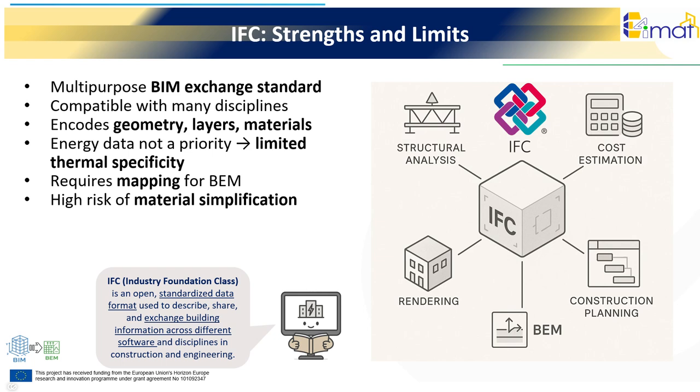If the BIM authoring tool did not populate those thermal fields, or if the mapping rules are incomplete, the BEM environment may rely on generic or simplified material definitions. This multipurpose nature of IFC is important to understand. It excels in coordination across disciplines, but it does not guarantee complete thermophysical detail, making careful data preparation essential for accurate BIM/BEM interoperability.